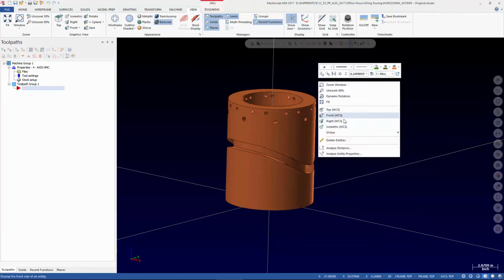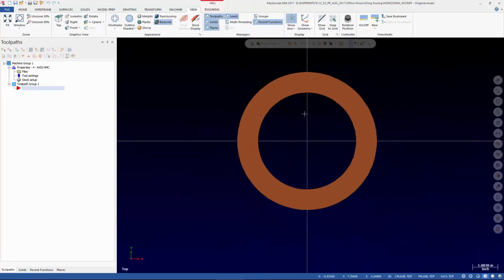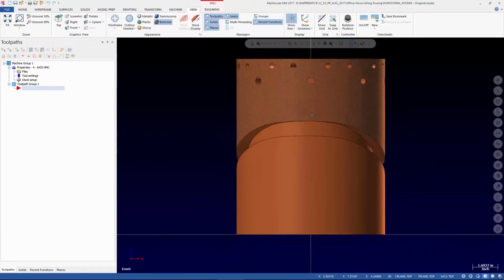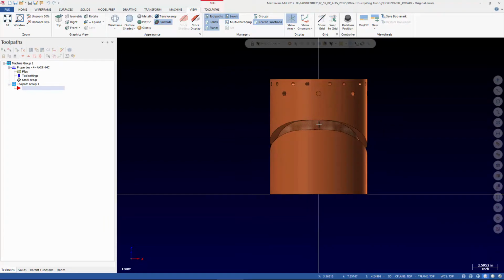But when we first look at this, here's the orientation. If we're putting this on a horizontal machine, then this would be our starting point. The reason that's true is that the front plane is the default 0 plane for horizontal machining with the generic Fanuc 4-axis posts.